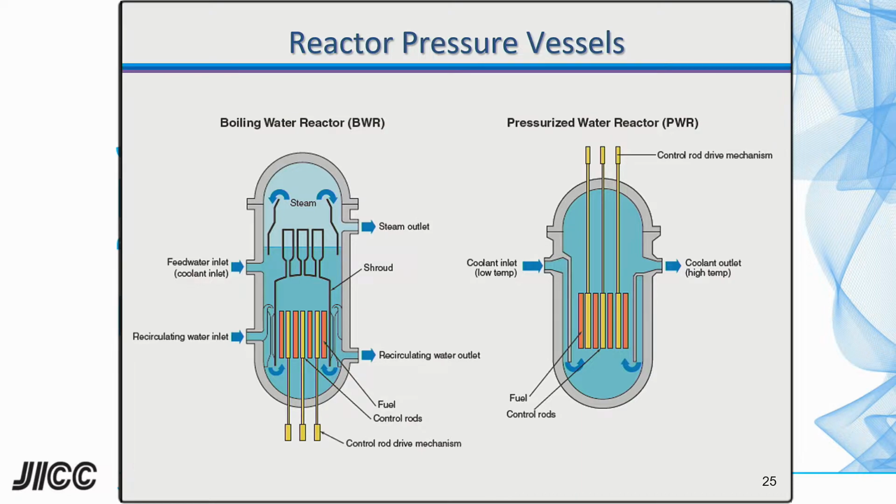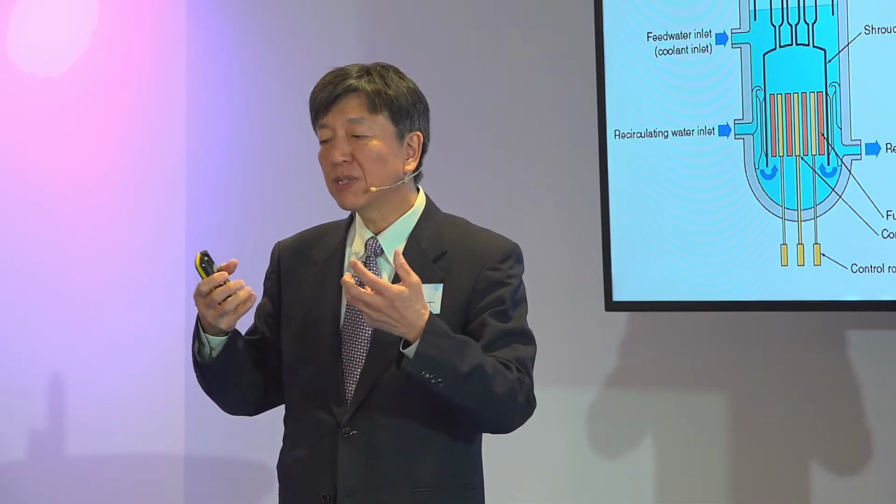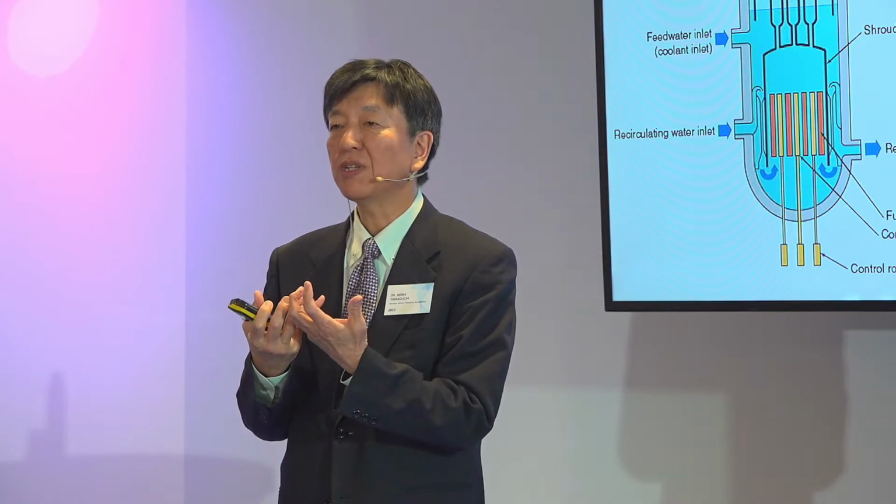And the next slide shows the reactor vessel structures of the light water reactors, PWR and BWR. Already I mentioned that in the PWR, the system is pressurized and single phase. So it's easier to understand, right? Single-phase water. We can rely on its coolability. When we look at the history of light water reactor development, as you know, the PWR was developed first because they were not sure if two-phase flow in a reactor system could safely remove the heat. But in the United States, they started the BORAX experiment, where they found that if the water boils into vapor, of course, the coolability decreases.